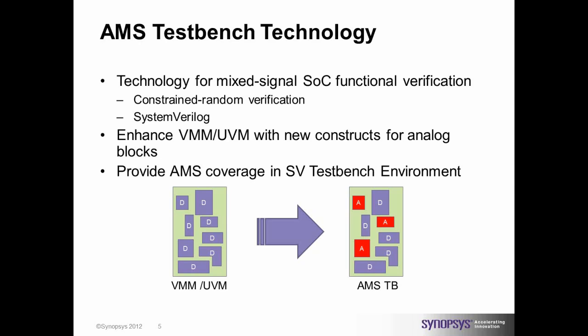Right. So technology for mixed signal SoC verification should be able to leverage constraint-random verification and advanced HVLs like SystemVerilog. The idea of this package is to have the methodology enhanced with new constructs for analog blocks and be able to provide AMS coverage in a SystemVerilog testbench environment.